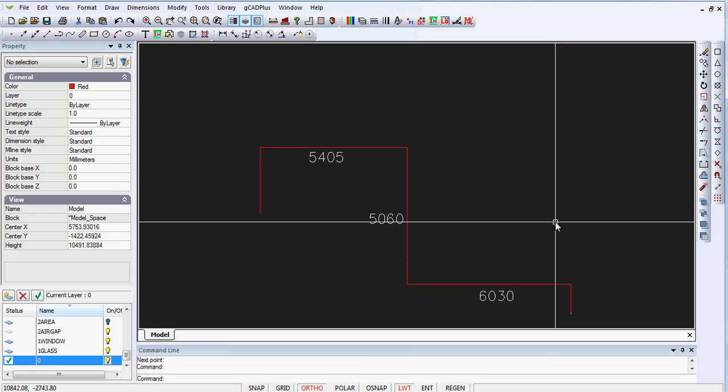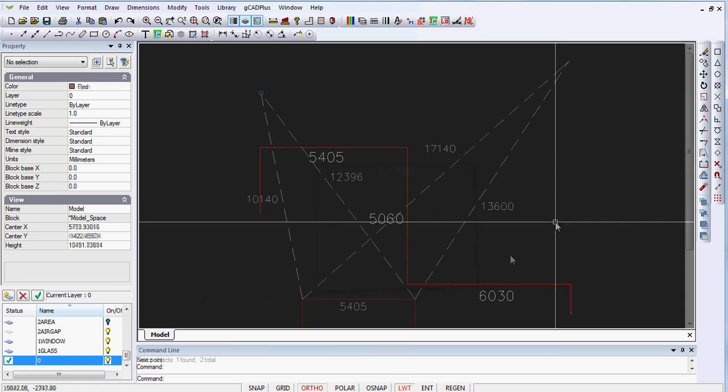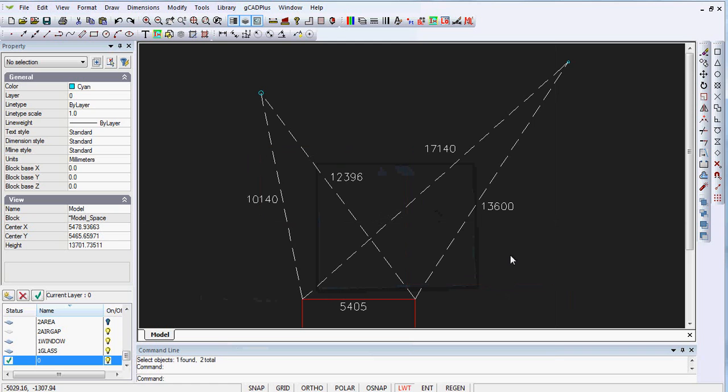The next thing to do is to set up the boundaries on the left and across the back and down on the right-hand side. The next step might be to accurately locate the boundaries. Let's imagine that this side had a back fence that sloped up at an angle through here. So on our mud map, we've done some triangulation. We've measured from this corner of the house up to the corner of the block, and we've come across to this next corner of the house and measured another length there.